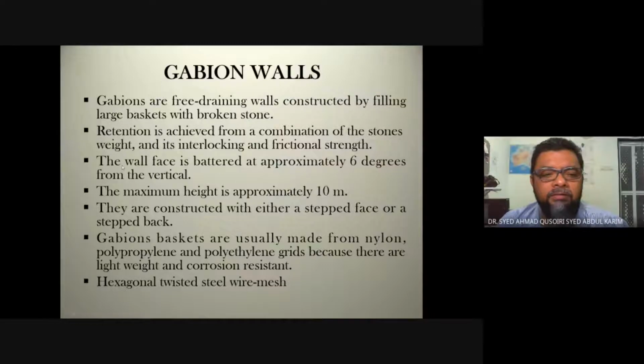Then the wall face is tilted approximately 6 degrees from the vertical, okay. And the maximum height is 10 meters, okay. So either a stepped face or a step back with certain angles, okay. So the basket itself is made out of nylon, polypropylene, or polyethylene grades.